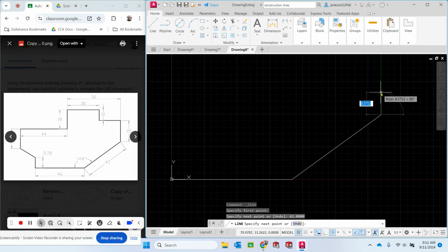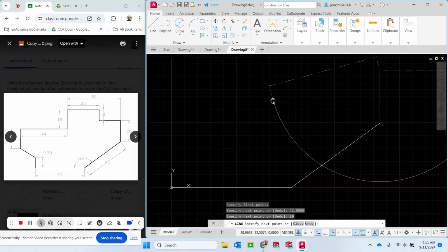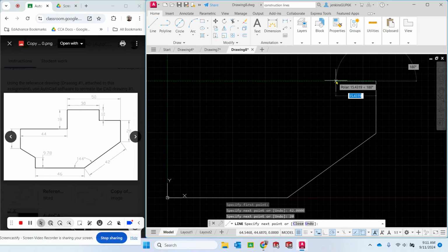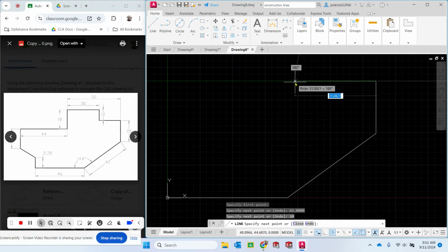and it's done. At this point, this next part becomes pretty fast, right? Because this is just a matter of drawing straight horizontal and vertical lines. I know that this line is going straight up. I can see that my green line is highlighted, making sure that it's vertical. If I type in 20, enter, it's going to draw me a 20 line. Next one here is going to be 20 because 50, the distance from here to here, minus 30, the distance from here to here, must mean that this part right here is 20. All right, so I go horizontal, type in 20, great.